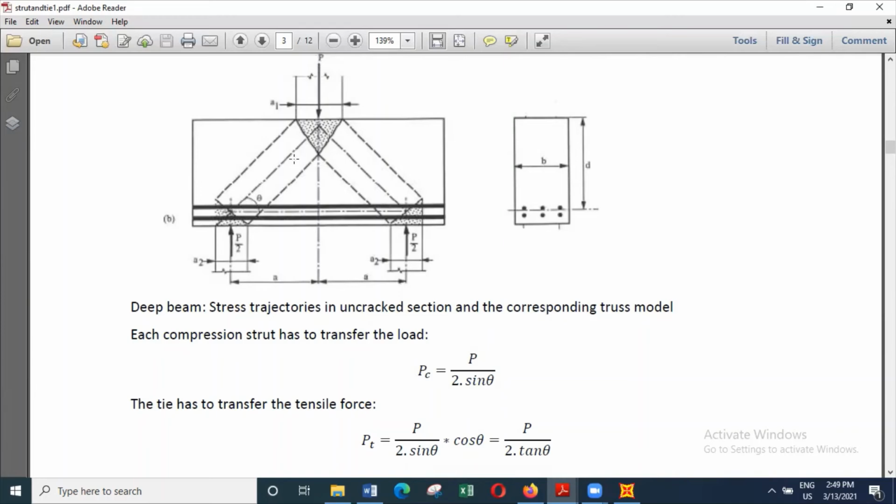And in addition to that, because these loads are now in this direction, to prevent the failure of this joint, you have to provide tension reinforcement this way. So here you get tension, here you get compression, here you get compression. So you get a situation which is different to this place. At this place, you get compression this way, compression this way, compression this way. Whereas here, you can see there's one compression, another compression this way, and the other one is tie force.